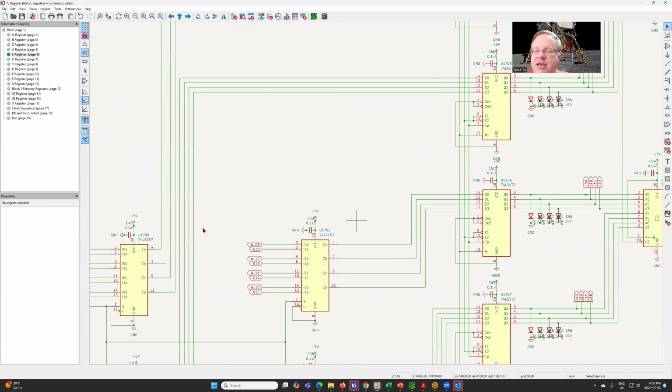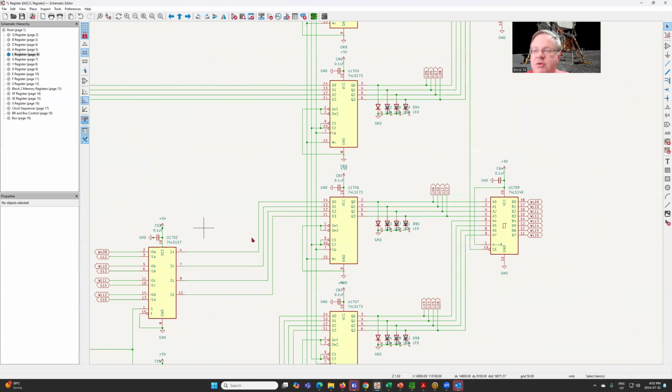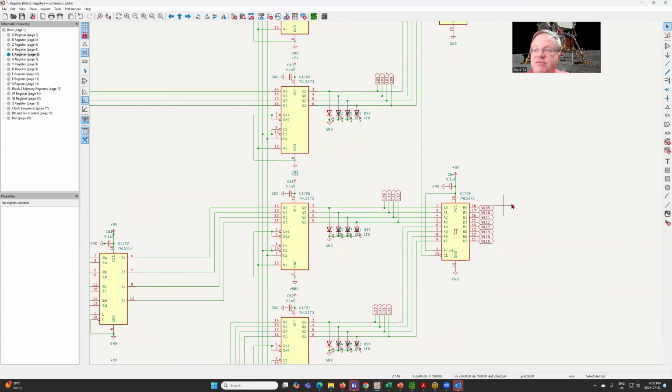There's also a reverse control pulse, which loads data from the L register into the G register. So we'll also have a jumper that makes the L register contents accessible to the G register. Now that means we have the contents of the G register available on this board for the L register.